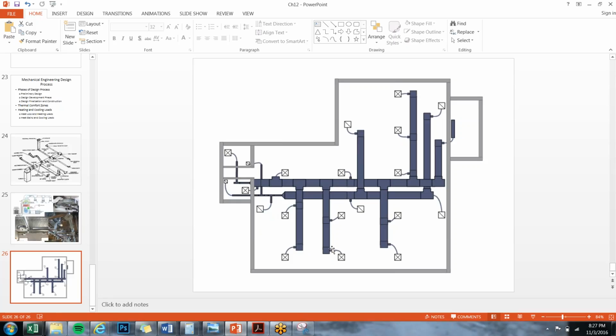And then notice from the screen too, these are the quick and dirty details that I'm giving you right now, because your book does a great job at all the fancy stuff, but I want you to know what we actually have to do at the end of the day for the drawings. Okay, so this is what your drawing will look like minus the connections. So here's with the connections, and then notice the biggest thing about this. There's more of the diffusers, so they output into the actual rooms, than there is the return back in to circulate it back through. We have almost 2 to 3 times the amount of diffusers to returns.